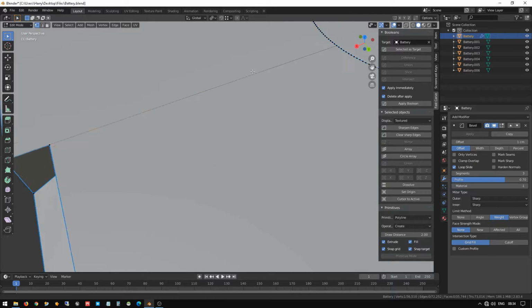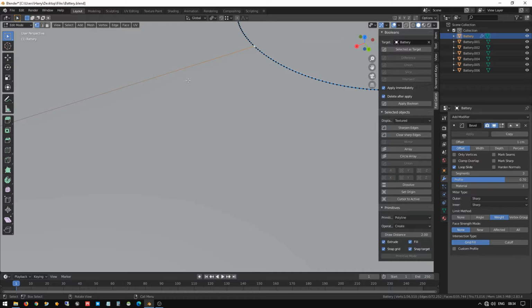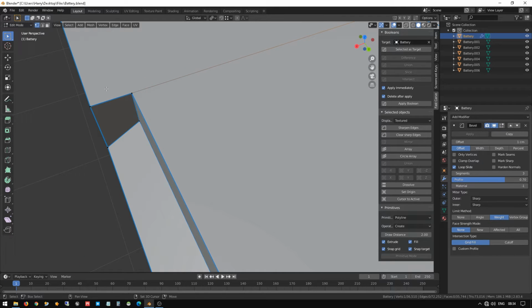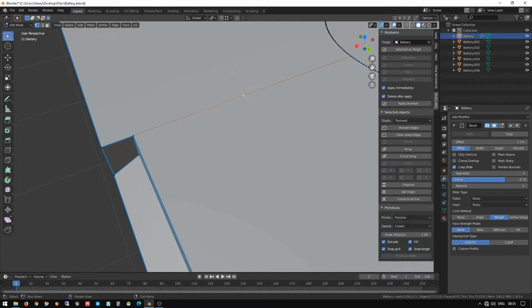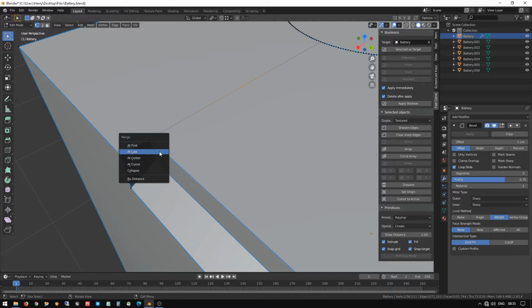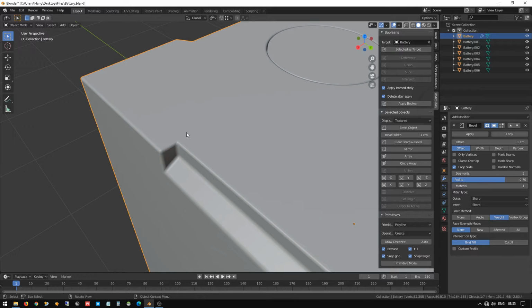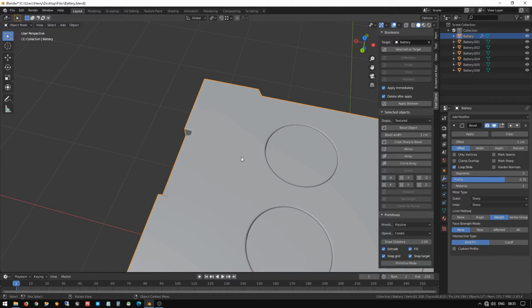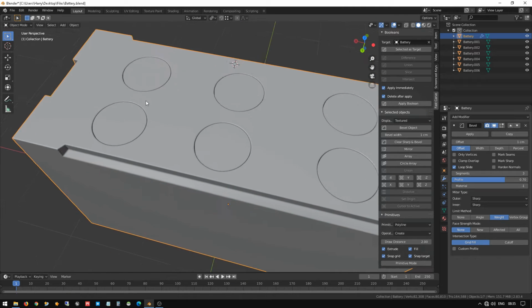and this vertex and this vertex, right click, and subdivide, and here you can see one vertex point is created using the subdivide. Select that and select this vertex, press M, merge it at last. Now we can see that option is gone. So this is how to clear that error message.